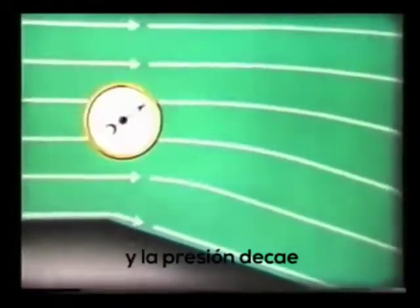This supersonic wing section has another kind of sharp corner. Here, just the reverse happens. The streamlines move further apart, the speed increases, the pressure falls. After turning the corner, the streamlines are parallel to the new surface. This is called an expansion. How does it happen?